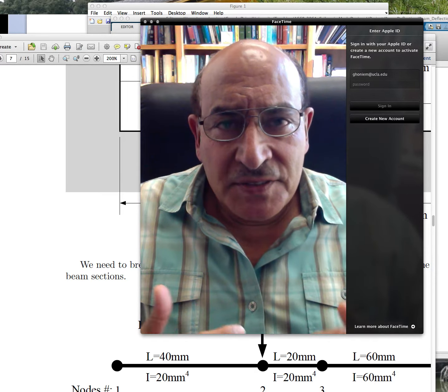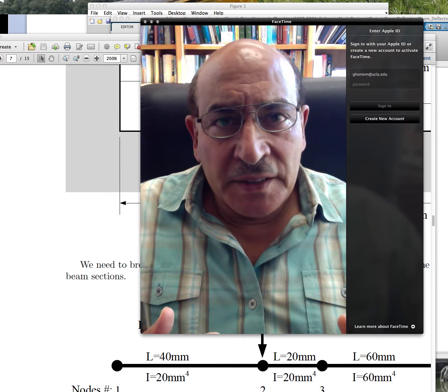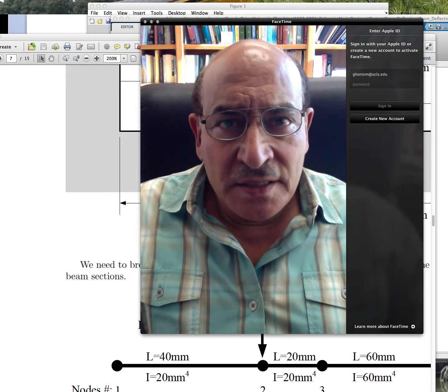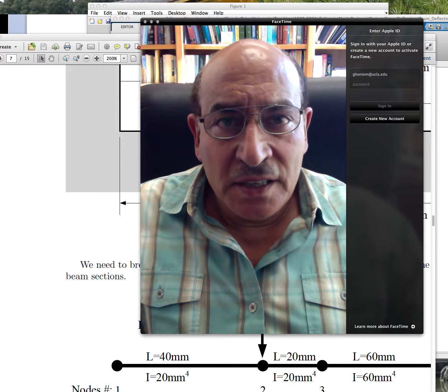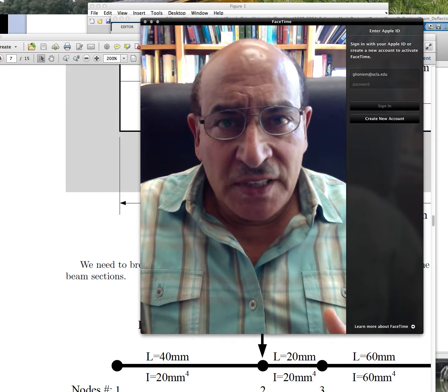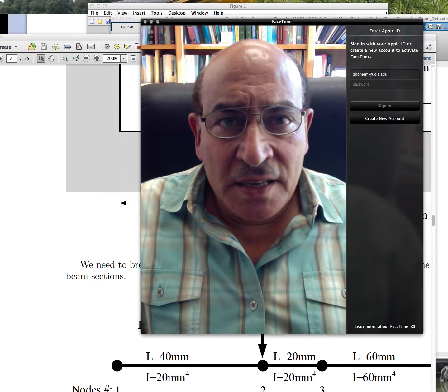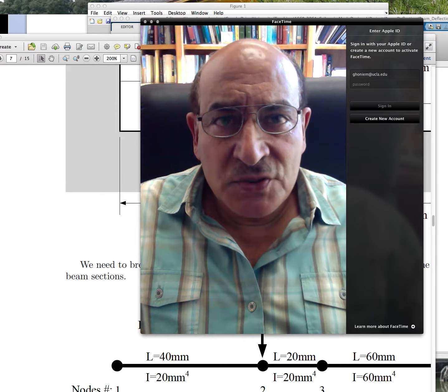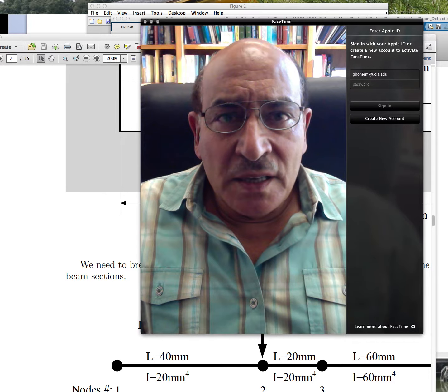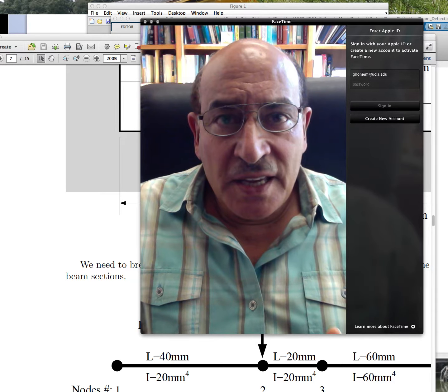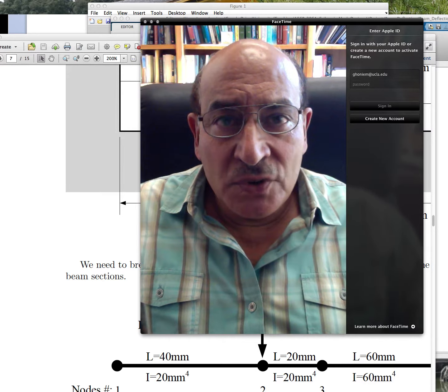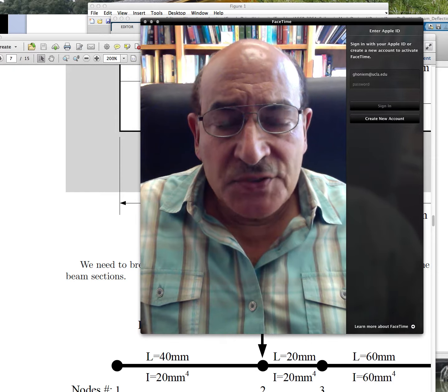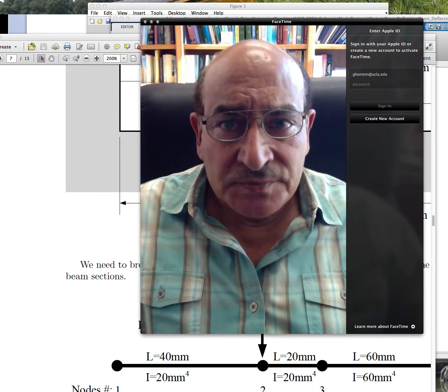As we know, shafts have to be rigid, and they have very strict requirements as far as the slopes or deflections that they would incur. Therefore, we need to continue our discussions of stress limits, which we have satisfied so far, with another level of design to see if the diameters that we've selected for our example shaft are actually satisfactory as far as the deflection is concerned.